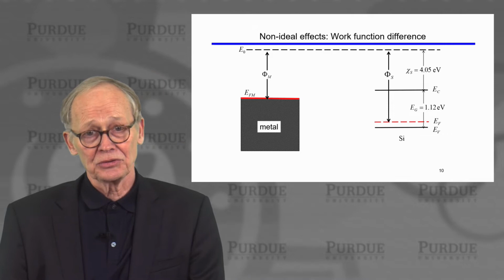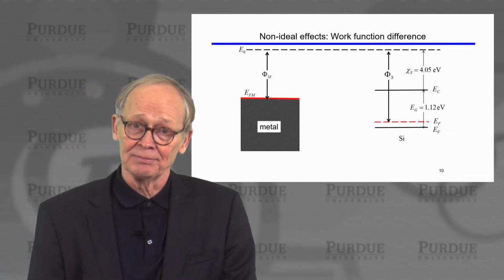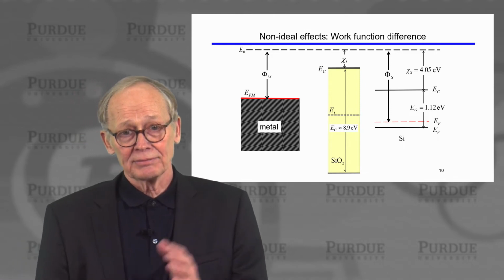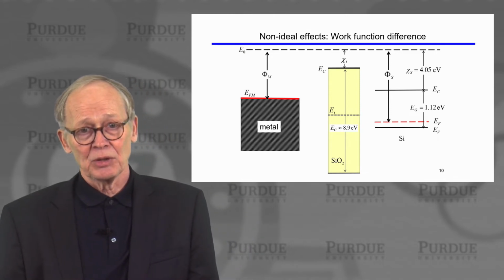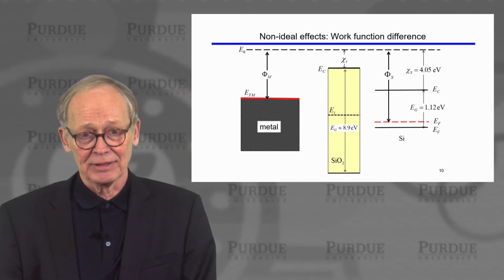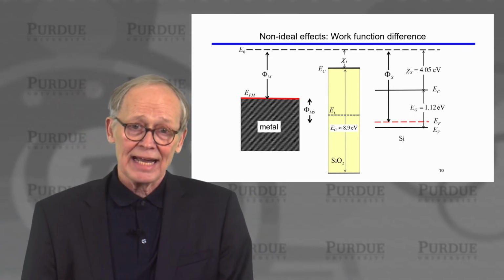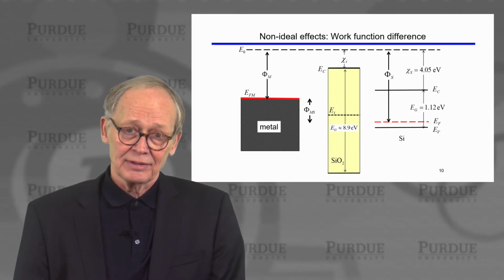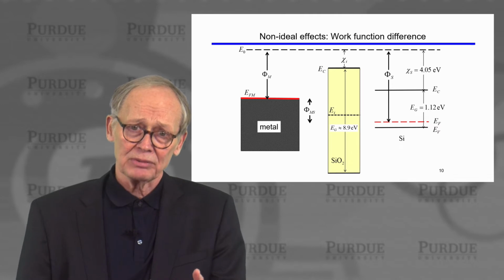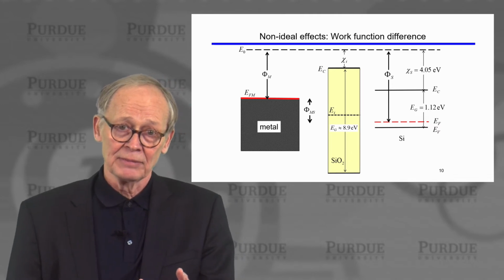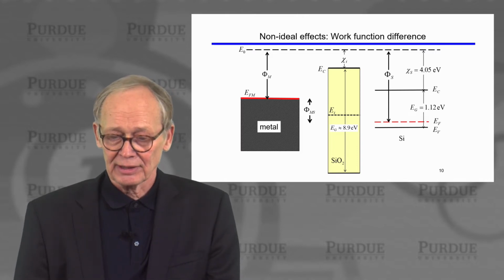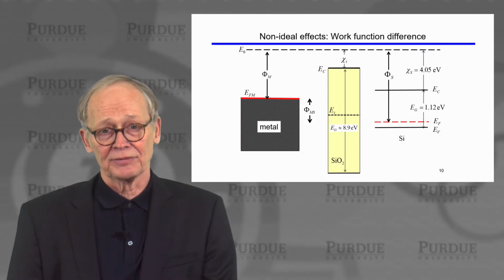And the chances are those two work functions are not going to be the same. When we put this metal, insulator, and semiconductor together and we're in equilibrium, there has to be one Fermi level constant everywhere. How is that going to happen? Well, that happens because a positive potential develops on this gate, a built-in potential there even in equilibrium, which lowers the energies in the metal gate, pulls this Fermi level down so that it aligns with the Fermi level in